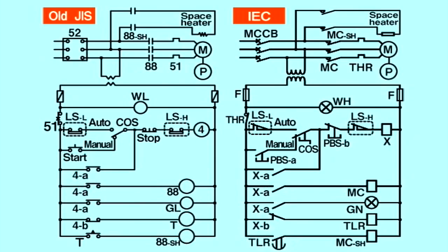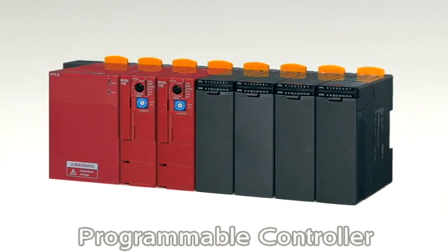In the sequence control circuit, the control circuit is composed of mutually connected devices such as switches, timers, and control relays. Because of this, the circuit wiring becomes complex, making it unsuitable for complex control tasks. On the other hand, when a programmable controller is used, connecting most devices to the programmable controller will suffice, making wiring much simpler. Moreover, in some cases, only the program has to be rewritten, even when the controlling method has been changed, eliminating the need to change the wiring.